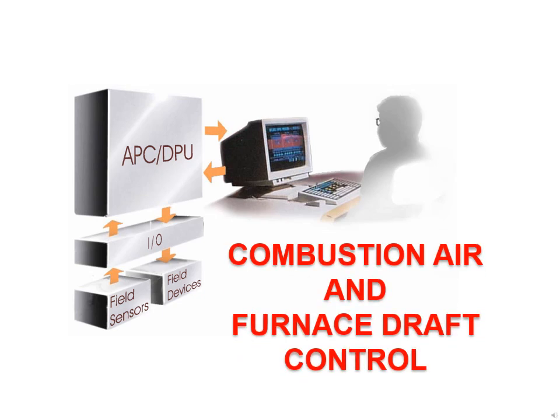The purpose of any combustion control system is to safely and efficiently maintain the desired boiler output without the need for constant operator attention. Therefore, the combustion process inside the furnace must be controlled while the boiler output changes in response to load demands. The basic principle of combustion control is to meet the boiler load requirements by regulating the quantities of fuel and air while achieving the optimum combustion and maintaining safe conditions for operator and equipment.